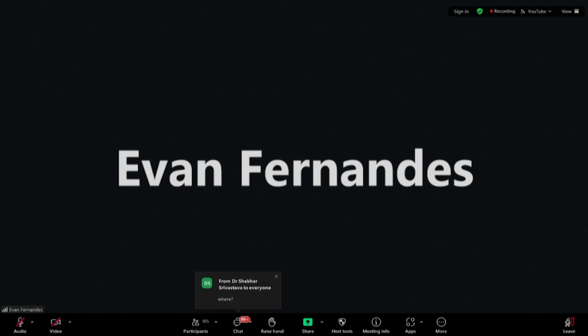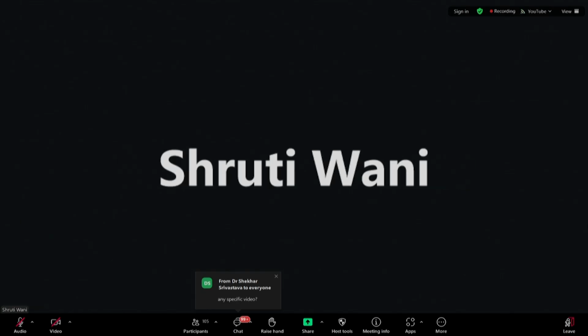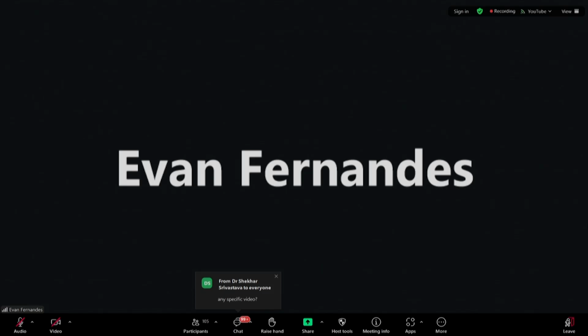Or when you're loading it in ParaView, just check whether you're loading the proper file. Or you can manually do a touch .foam. You can create a file named .foam, and then open that in ParaView and see whether it is at least opening that particular file of yours. Can you please repeat it once again? Okay, so try first cleaning the whole case. Do an Allclean, the bash Allclean which is already there in the folder. Do that and run the simulation again and see if the simulation is giving any error.